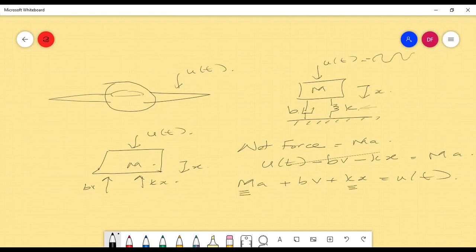All right. There are cases where the differential equation will come out oscillating and getting bigger and bigger and bigger. You don't want that. You don't want the k value and the m value, with the weight of the wing, to be such that it is going to oscillate out of control. You're going to want what is called critically damped.